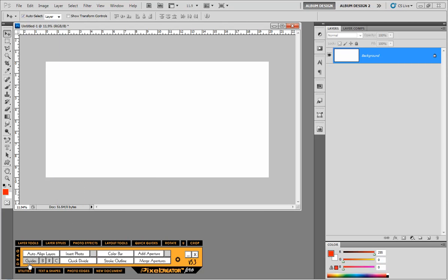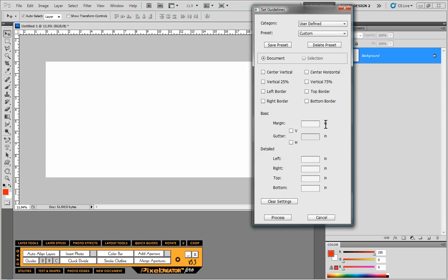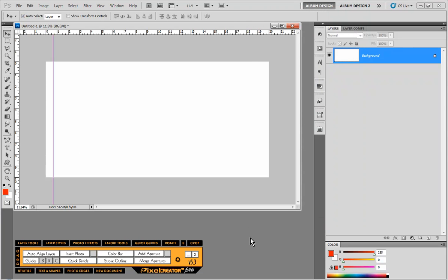Now, what if I click on guides? Remember I said here it defaults to inches because my current document value is set to inches. If I were to come in from the left edge 200 pixels, so I type in pixels to overwrite the inches, now I get a guideline exactly 200 pixels in from the left edge. So if we're doing web layouts or something like that, where a certain dimension would be nice to have, that is an option. We can override the default unit values.